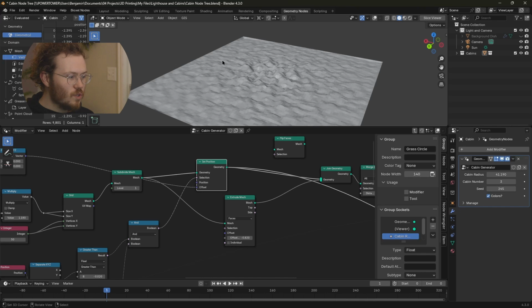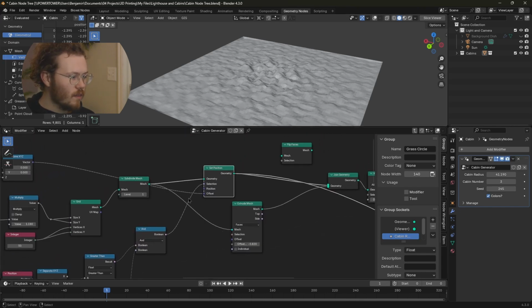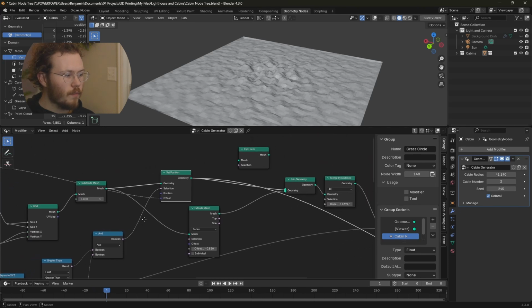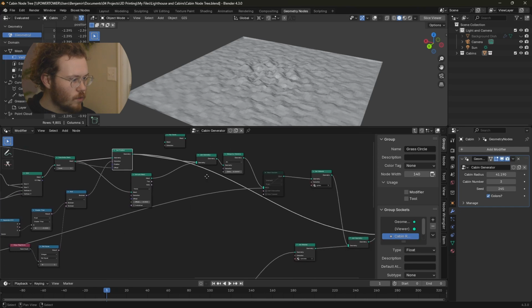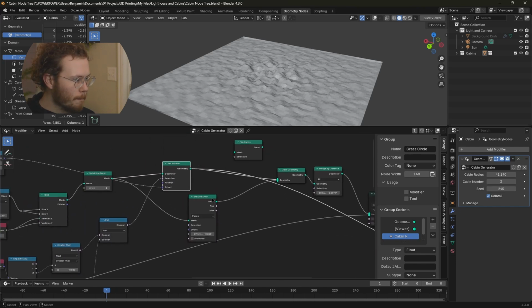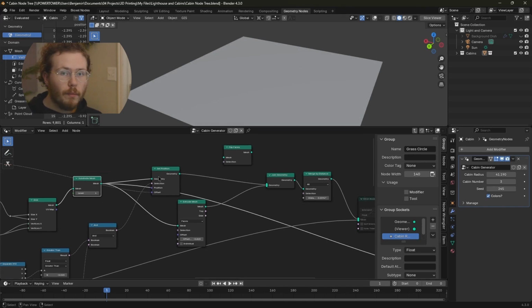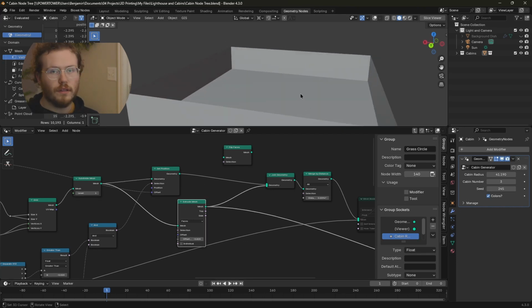And so that's really slick because what it's doing is it's selecting all of the vertices except for the edges to make this transform. The reason that's really slick is when we go to extrude it, what we're going to be doing is we're going to be extruding this mesh. And if you remember when we did an extrude earlier, I said that it only extrudes the sides and bottom, or the final shape, and it excludes the original.